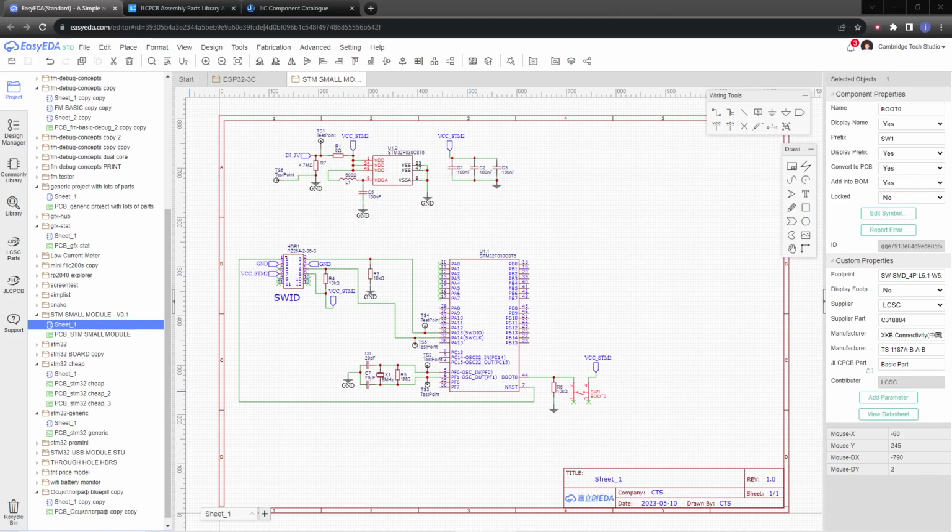So today I'm going to be talking about working with JLCPCB for PCB production and assembly. So we're going to be ordering the board and the parts, and they're going to assemble it. We'll want to work with them to make sure we're using the components that they normally stock. We want them in stock, and ideally we want them to be at a good price, and that normally means we'll be selecting items from their basic part selection rather than their extended part selection.